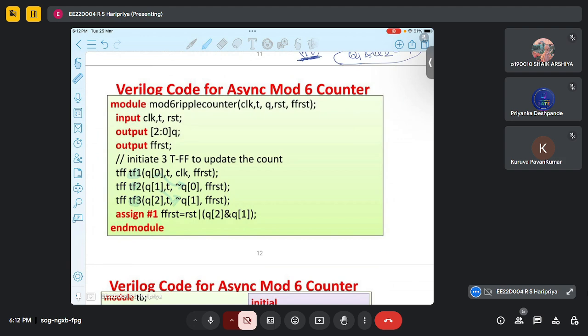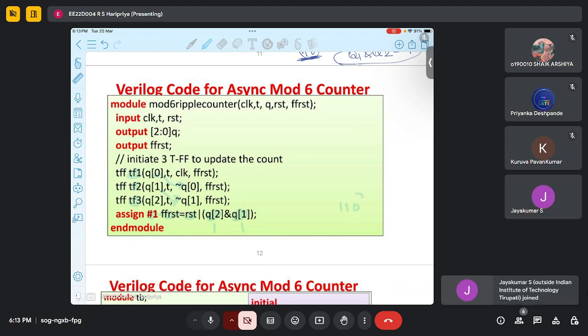And after some delay, we have a reset, which should perform the reset operation either if it is reset or when Q1 and Q2 are both 1. Because when we get 6, the counter should perform the reset operation.